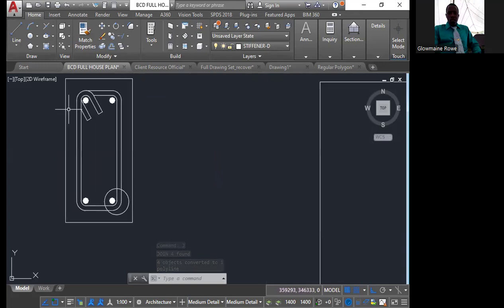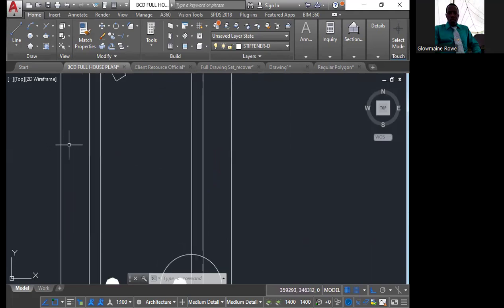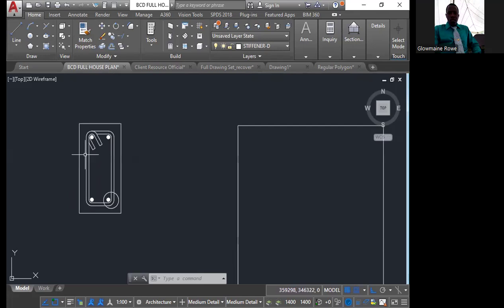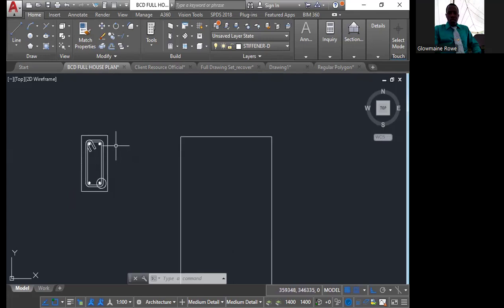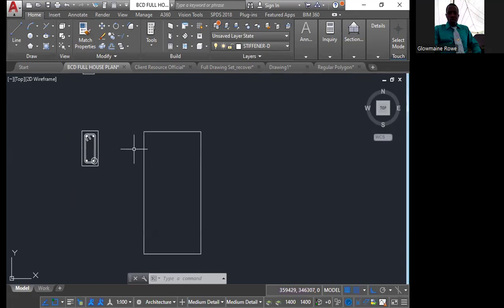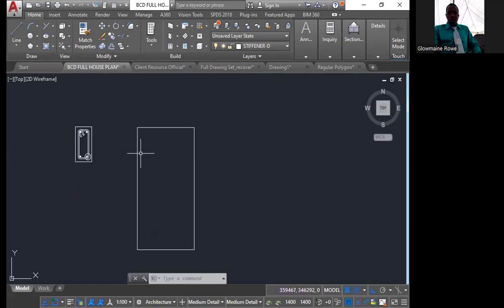And we said that for your steel caging, you need a minimum concrete cover of 2 inches. I believe recently the building code has changed it to 3 inches. But most people, as far as I know, probably still work with the 2 inches. So 2 inches is gonna be 50. So we're gonna offset inwards.